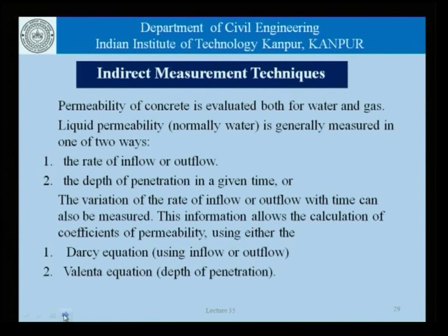One is by the rate of inflow or outflow, and the other is by a depth of penetration in a given time. We will talk about these two tests a little bit in the next slide. They help us establish or estimate the coefficient of permeability of the concrete based on either Darcy's equation or the Valenta equation from the depth of penetration.